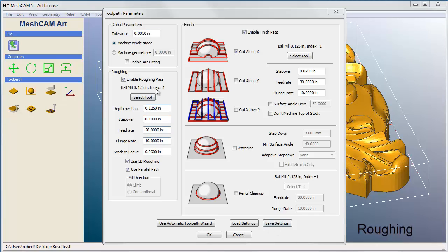Okay, so now we're going to move on to roughing over here. The roughing toolpath is going to be used to remove the vast majority of your material. When we look around the part here, we told it to machine the entire stock. So roughing is going to be removing everything around the part, minus a little bit. We're going to tell it over here how much we want to leave behind, but it'll remove everything but your core part plus that little bit to leave behind for finishing.